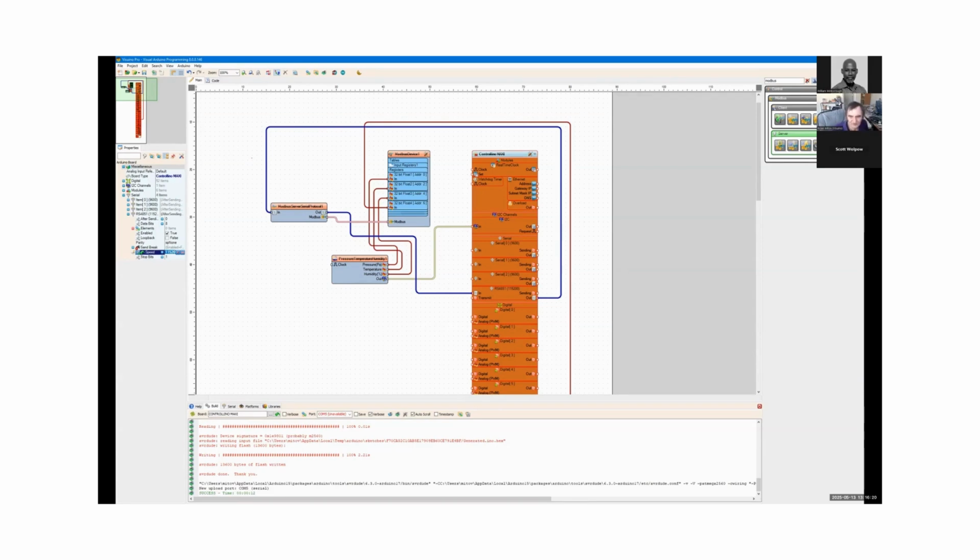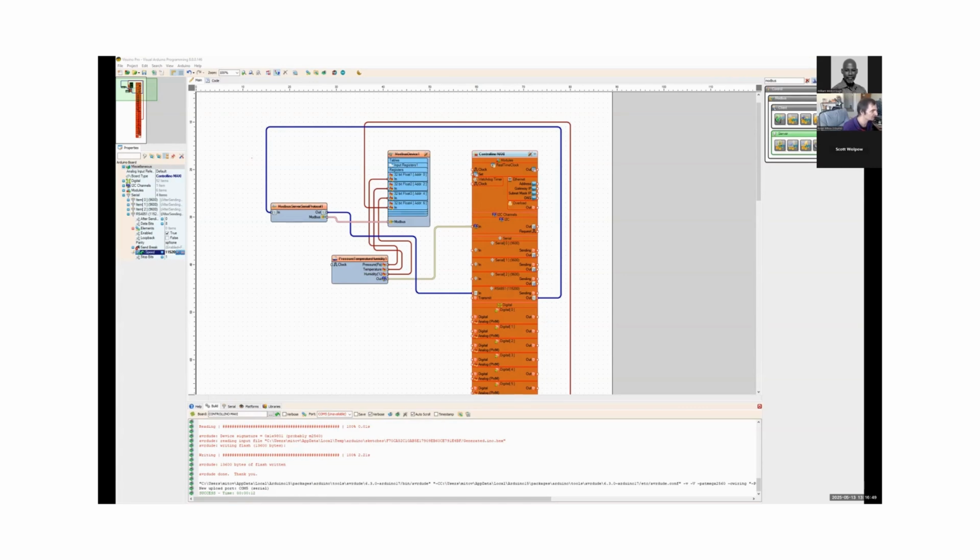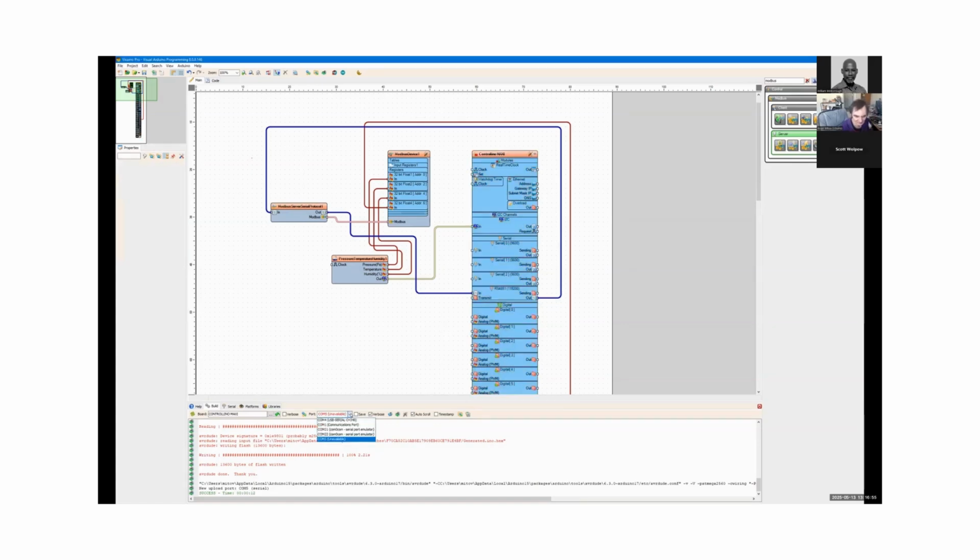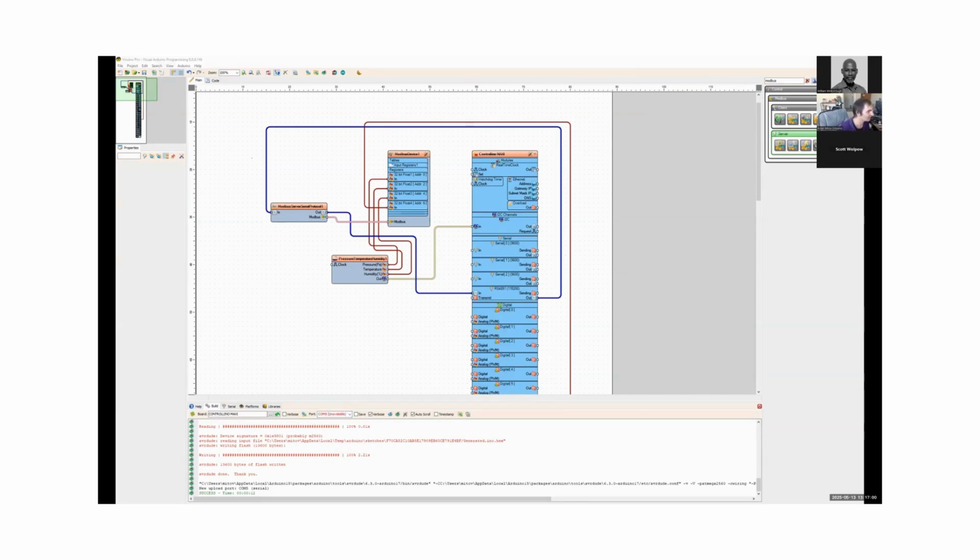Now what we can do is I have a Modbus tester here, which I downloaded online. There are quite a few of them available. This is, put it on the right screen. This is called Razio. And the first thing we need to do is make sure we have the right protocol selected. So it's Modbus RTU. Everything else should be fine. Yeah, the port. Let me see what COM port. It came as COM port 4. Okay, so COM port 4.